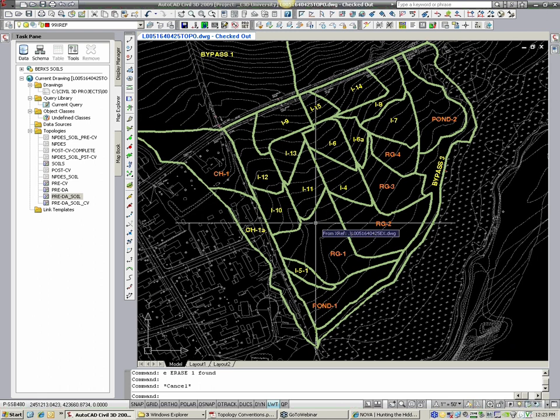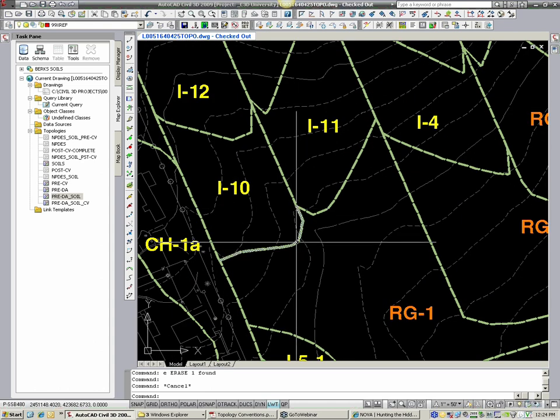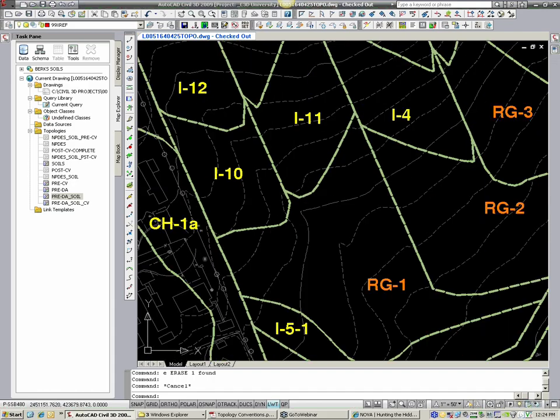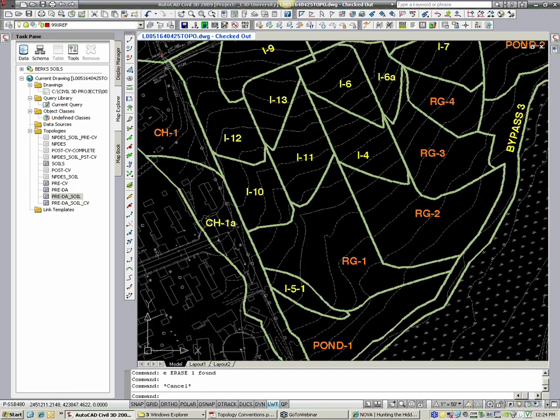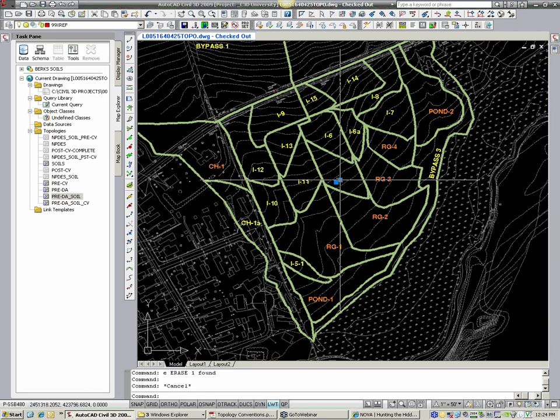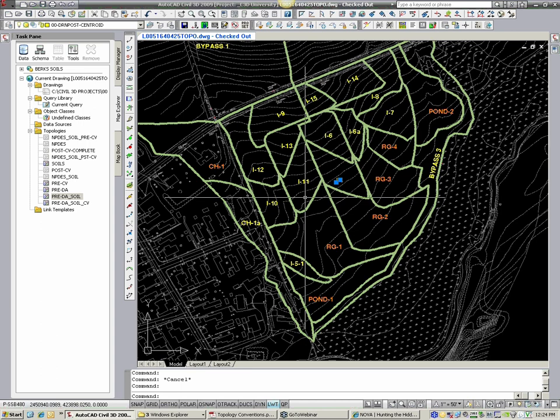So how I'm going to start off with every project is I'm going to map my drainage lines to the smallest aggregate. The smallest aggregate is going to be your inlets. So I'm going to draw my inlet drainage areas for every project. And once I have that done, I'm at this stage, and I'm going to put a piece of text again. This is just standard text, nothing special with it, to each drainage area map. And I forgot to do something there.